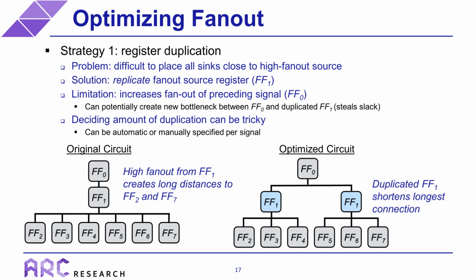One quick note about doing register duplication manually. Synthesis tools will, by default, synthesize away registers with the same functionality, which is what we have here with the duplicated registers. So the synthesis tool would basically get rid of all the duplications. So before you spend a bunch of time explicitly coding duplicated registers, make sure you look at how to disable this optimization in your synthesis tool. Or you can look at the Fanout code example on the repository where I will demonstrate how to do this for Quartus.